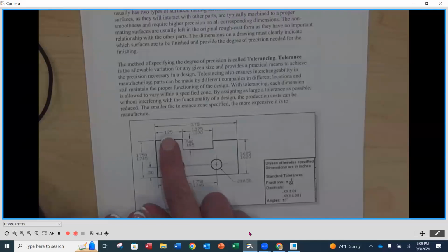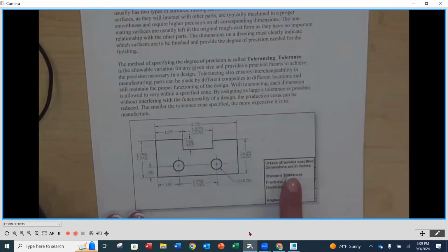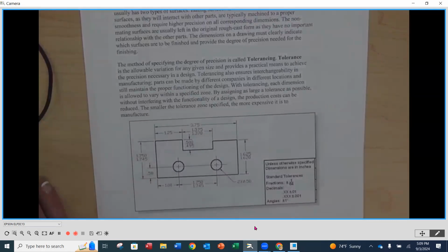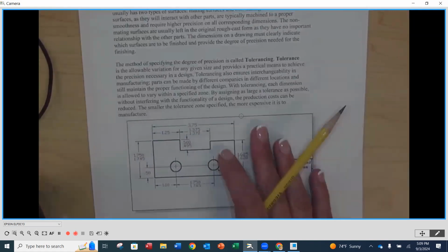If there's not a tolerance specifically in back of it, it is going to default to whatever the title block tolerance says, okay? But we also can place dimensions on here in limit form or having a bilateral tolerance. So we're going to review all those different ways of doing things so that as we're looking at the projects that we have coming up, we understand that when we have fits that are especially more critical to the function of our assembly, we want to be sure that we're specifying the right things. So we're going to be diving deeper into tolerances and specifying them and how to do that.